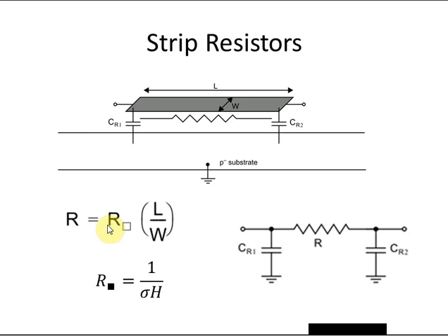When we're using polysilicon as a CMOS gate, obviously we don't want it to be very resistive, but when we're building a resistor out of it and we want some reasonable values in the range of a kilo ohm or a few kilo ohms or even hundreds of ohms, then most likely we're going to prevent that salicide from being applied, and we're going to get a larger value of 200 to 2000 ohms per square. Some manufacturing processes will provide special metal layers that are just designed to be useful as resistors.